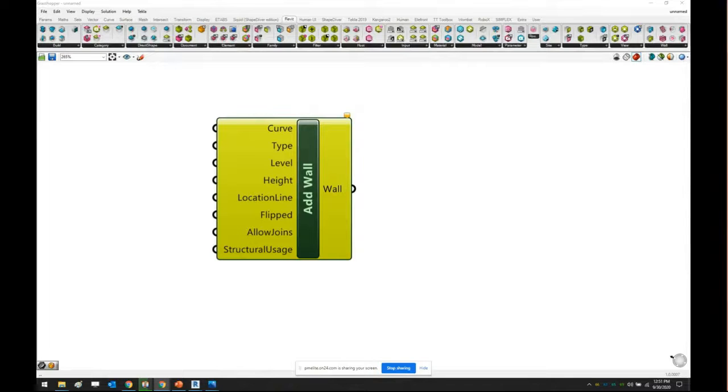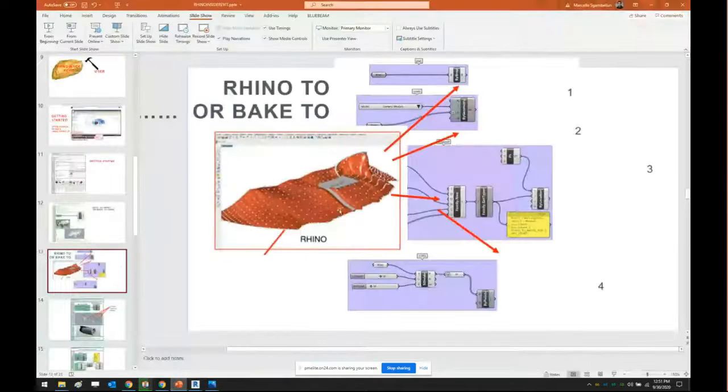Your block question? Oh, there is one thing I have to mention. I have found on some occasions, and I brought this up to the developers, that if your geometry inside of Revit is grouped together, sometimes it will not convert. So in that particular case, you need to explode it. Although I understand they're working on that issue right now, because I'm not going to tell you that everything is perfect, right? So if you can't find that it converts, it may be grouped. You may need to get it out of its group, or you may need to explode it, and then you could work with it that way.